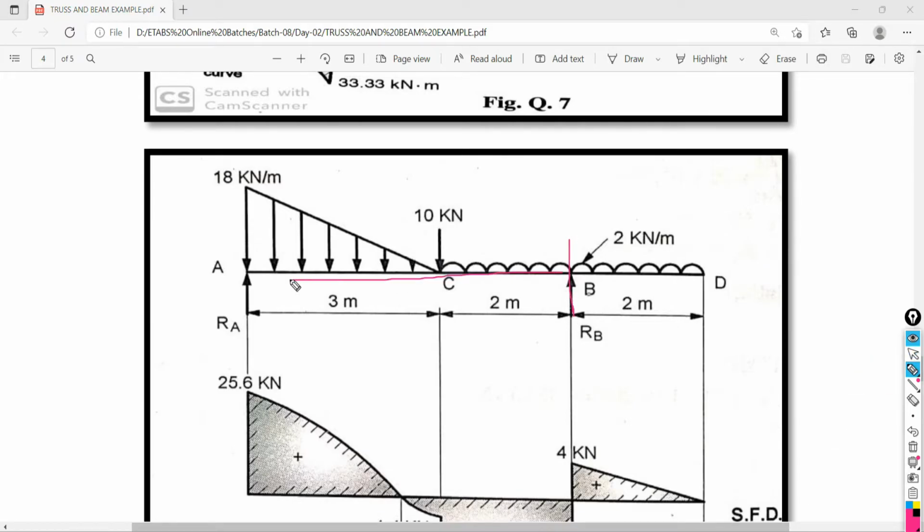Here the one beam is up to this point, and the other beam starts from here and ends here. Okay. So for this beam, is this uniformly distributed load a part load or a full span beam load? Tell me. Part of the beam. Okay. So how much intensity is there? Intensity is the same, 2 kilonewton per running meter length.